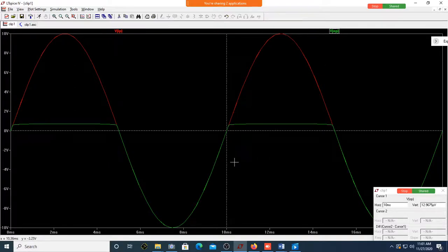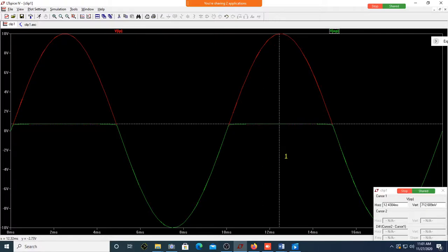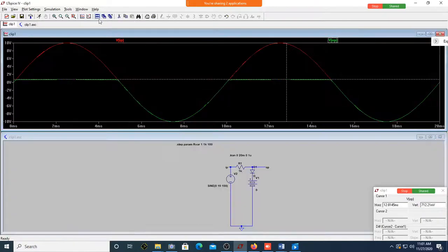Just here, actually the reference voltage is 0. But can you see what the output voltage would have been? Output voltage would have been 0 here. See here, this is actually 0. This is not 0 when the diode is on because the diode is not ideal. So when the diode is not ideal, the voltage across the diode is now 0.7. Yes, sir. That is what is being displayed here.